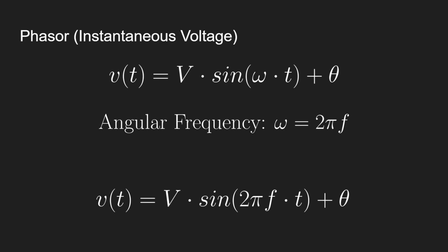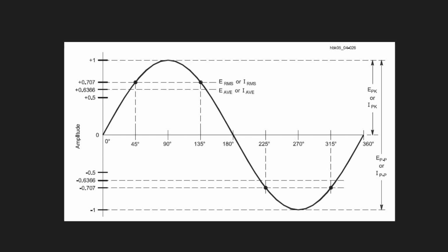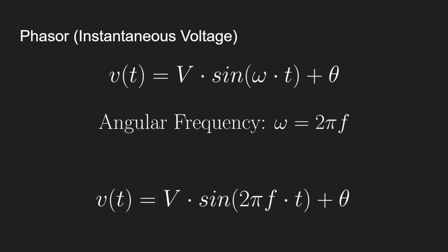Sometimes they may ask you questions like this: I have a sine wave here, they give you the initial starting angle and ask you at what time point, what is the instantaneous voltage of it. So you have to apply this formula, knowing the frequency of the AC or the signal. Sometimes the signal may not be a perfect AC. They may give you signals like our transmission, our carrier wave, which is at megahertz level. So you just have to apply this formula to it.